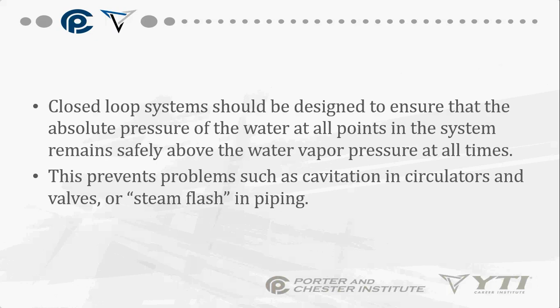We were talking about the Hartford loop and why it came about because of cold water getting backed up and then going into a hot cast iron thing, and then obviously it's exploding. There you go. That's why the Hartford loop was invented, yes. Because the first types of boilers that were out there were steam. They were steam boilers.